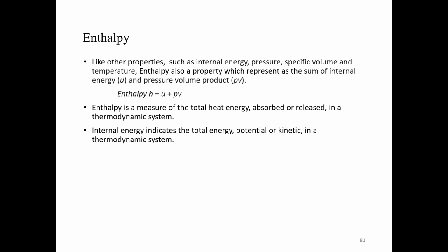So this is again a very important concept we call enthalpy, right? Like the other properties such as internal energy, pressure, specific volume, and temperature, enthalpy is also a property, present as the sum of the internal energy and the pressure volume product. So enthalpy we normally denote as H equals U, where U is the internal energy, plus PV, the product of pressure and volume, right?